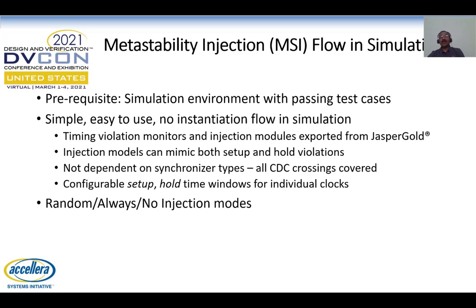The tool also allows you to do metastability injection in simulation. The prerequisite is to have a simulation environment with passing test cases. So it's a simple and easy to use flow which does not need any instantiation of any special modules into the design.